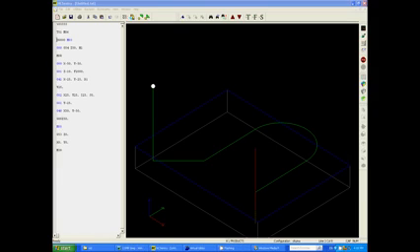Our next line of code will set the spindle speed to 6000 RPM. That will be loaded into the memory of the machine, but again the spindle will not turn on until it reads an M code, which is M03, to actually turn the spindle on. Now M03 tells the machine to turn the spindle on at the designated speed in a clockwise direction. Now, M04 is anti-clockwise.